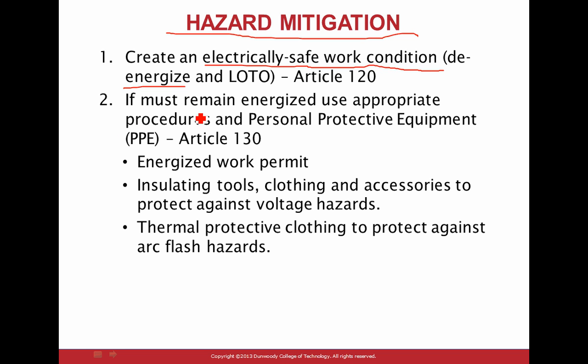And if it must remain energized, and you can't emphasize the word if enough, if you have to work energized, you have to follow the procedures and wear the PPE. That's the exception. Number 1, you have to do an energized work permit. You guys don't have to do it because part of what you do doesn't have a lot of energy in it. I don't know how you do it when you test a piece of equipment, because you do a lot of testing, especially when the energy is very low.